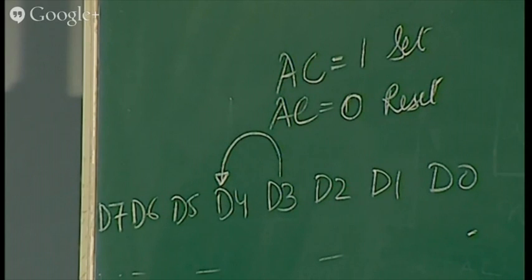Next we come to switching register banks, as I've already discussed, that PSW.3 and PSW.4 is used for switching the registers. In case both are 0, register bank 0 will be selected, in case 1, and accordingly. These are the 8051 registers. I've already told you about them. R0 to R7. These are general purpose registers.